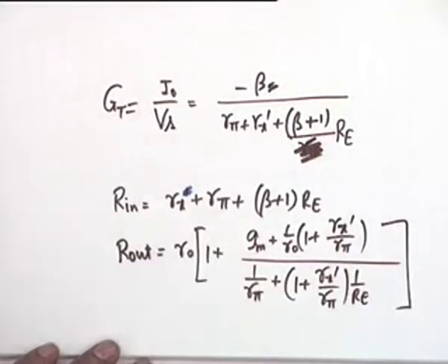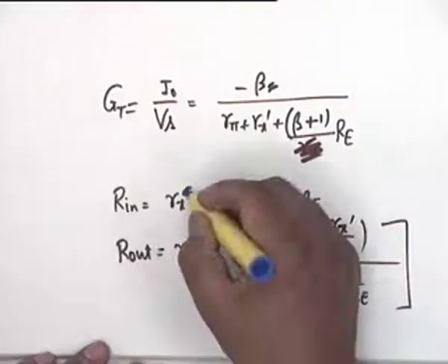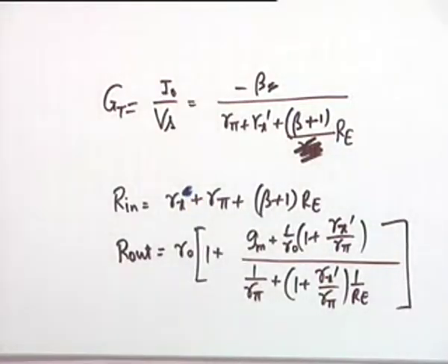Is Rx the input resistance seen by the source, or what is Re? Oh, thank you. This dash should not be there. It is the resistance seen by the source along with its internal impedance, that is the Vs-Rs combination. So this dash shall not be there. R out similarly is the resistance seen by the load, and therefore it does not include RL.